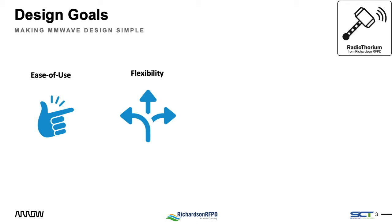Flexibility. Our unit is full of features. It will provide the design engineer with different ways to configure and program it, create MIMO configurations by stacking up multiple units if needed. It will have options like onboard LO and frequency reference generation, as well as the option to inject external LOs and synchronize from an external reference, and many, many other features we are going to touch on later in this presentation.